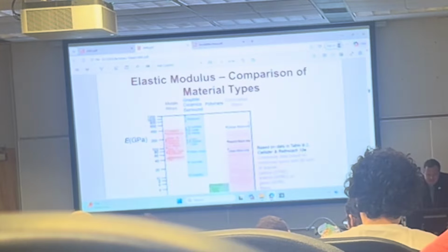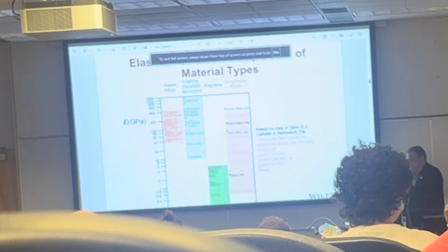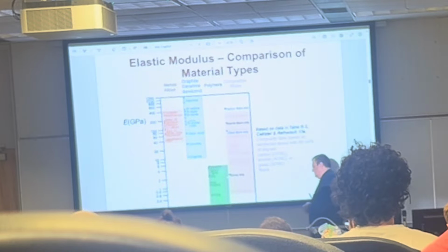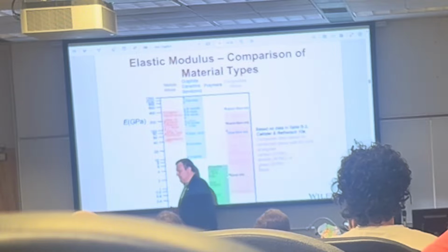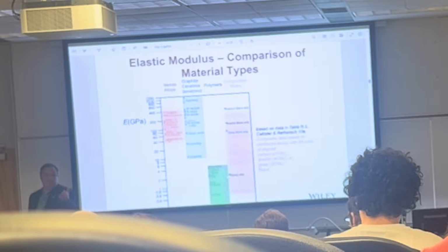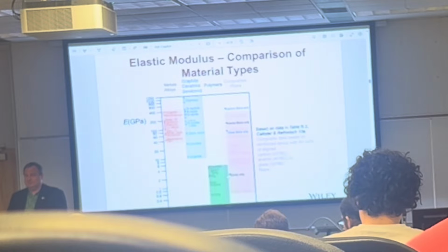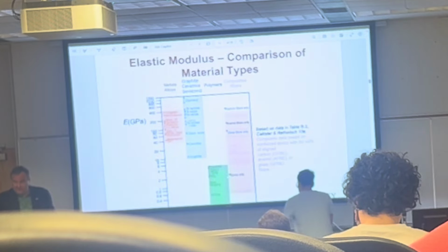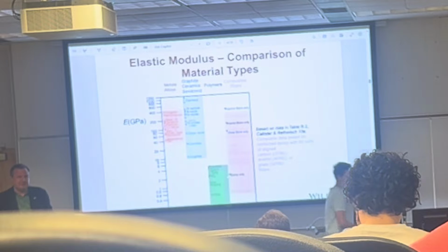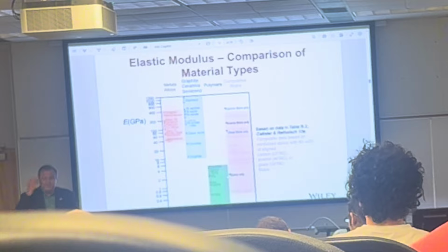Now we discussed elastic properties, which is the ratio between the stress and strain, proportionality constant using Hooke's law. The same principle that this load cell that I'm passing around is also using, Hooke's law. It's using the spring constant of this device to measure the load. But it's actually measuring displacement. And you can see that very well in that specific device, which is why I bought it, so that I can show it to students.